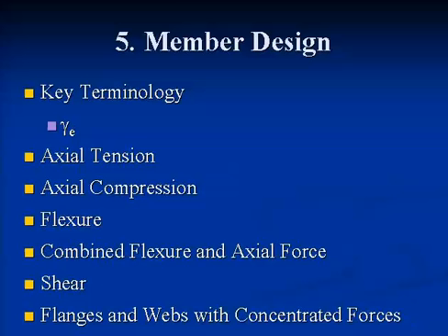We have a special term that we use quite a bit called gamma E, which is kind of the fundamental thing that we use to pull together the elastic stability of tapered members. And that thing is the factor by which you would multiply the loads in a tapered member to find the elastic buckling state of the member. And it gets used in a lot of the subsequent calculations.